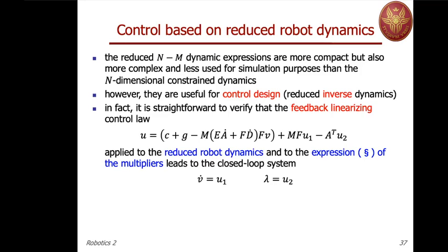the desired inverse dynamics. If you want to close the loop around this, then you will add an integral error on the lambda, and we will see this more in detail when we are dealing with hybrid force motion control, and you will add the PD term on u1, so not only the desired tangential acceleration, but also an error with respect to the tangential velocity and to the tangential position, once you have specified a timing law through which you would like to move along the circle.